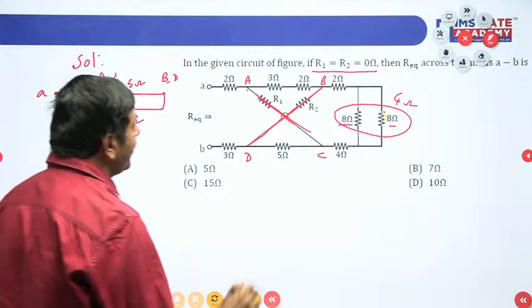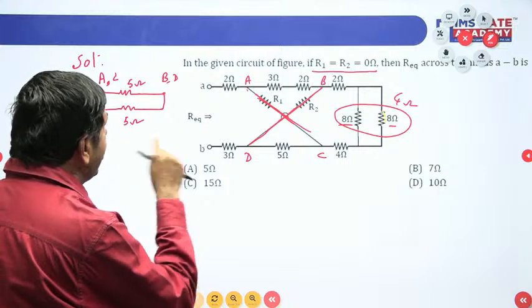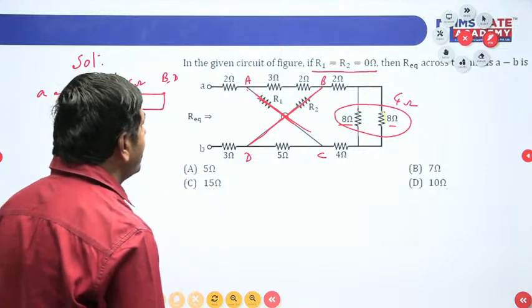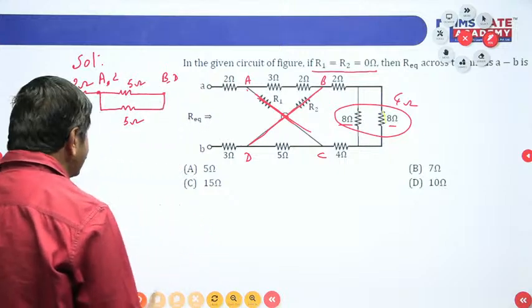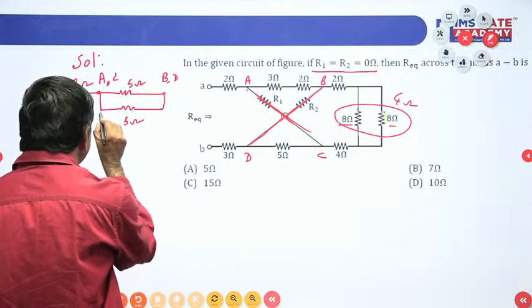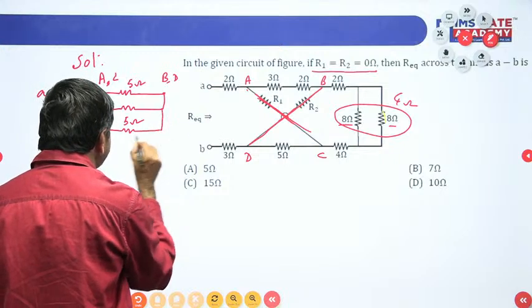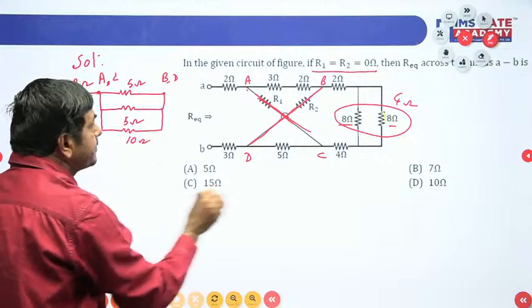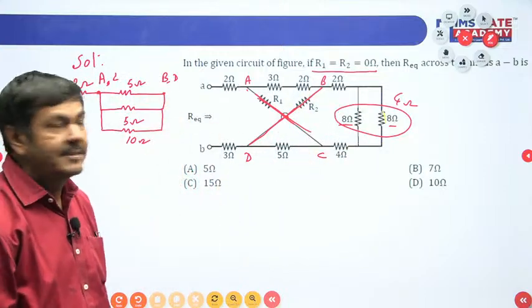Okay, we can connect that point only now. This is a 4, this is a 2, we got now. I can write directly 4 plus 4, 8. I can write 10 ohms we are getting totally. This becomes a 10 ohm resistor only now. This can be taken as a 10 ohm resistor. This is between B and C. Yes, B and C also that point.